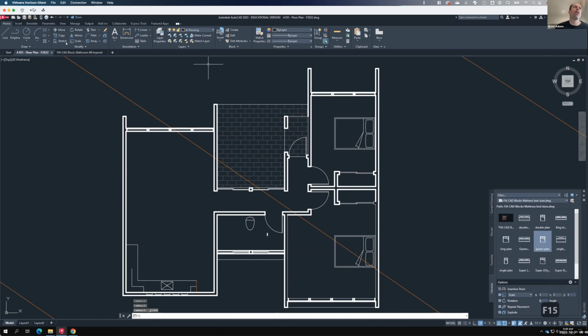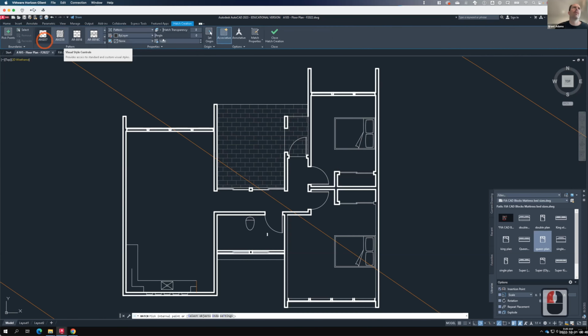And now that it's been saved, we'll go back into the hatch tool right here. And I'm going to go back to the diagonal flooring, just the simple diagonal. We're going to rotate by 45, and we had it at a scale of 20. And I'm going to try to put it in this room. So in this case, when I click and put it in, it did a pretty good job of recognizing the bed. So I'm reasonably happy by that.